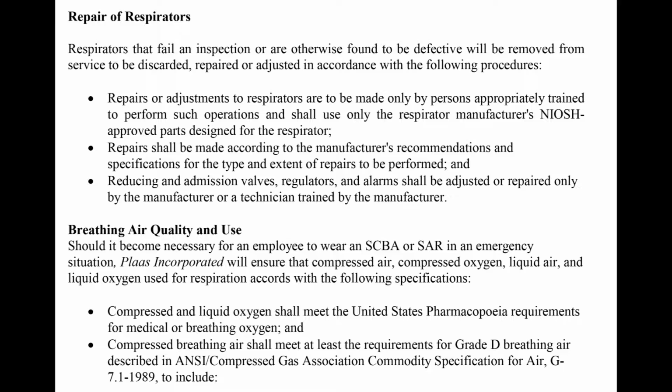Breathing air quality and use. Should it become necessary for an employee to wear a SCUBA or SAR in an emergency situation, Plaas Incorporated will ensure that compressed air, compressed oxygen, liquid air, and liquid oxygen used for respiration accords with the following specifications. Compressed and liquid oxygen shall meet the United States Pharmacopoeia requirements for medical or breathing oxygen, and compressed breathing air shall meet at least the requirements for grade D breathing air described in ANSI Compressed Gas Association Commodity Specification for Air,